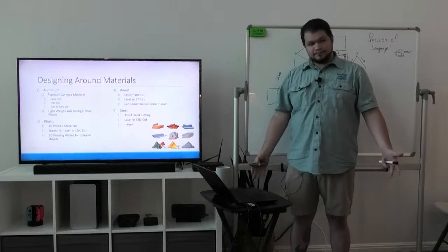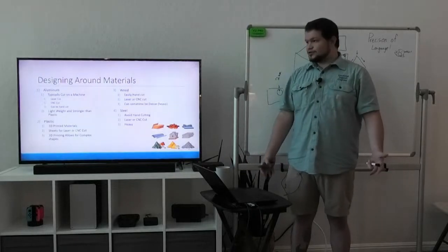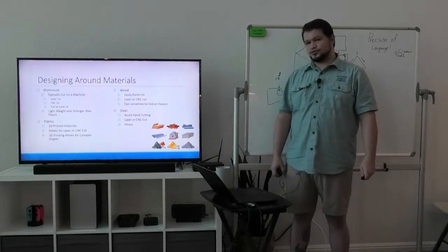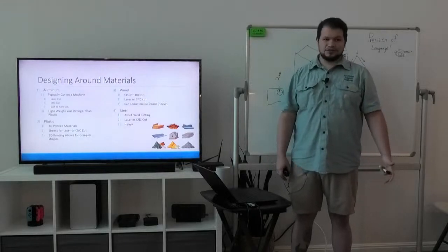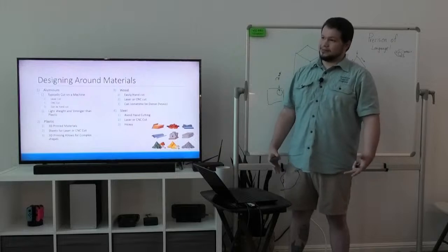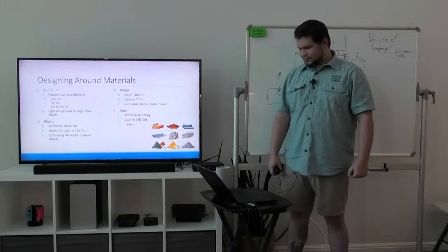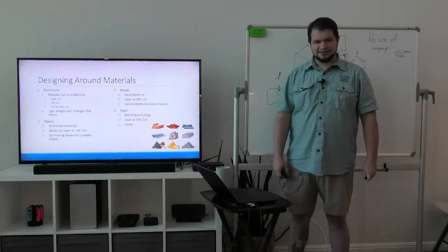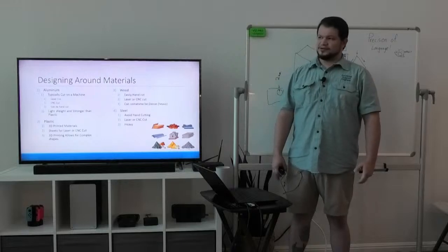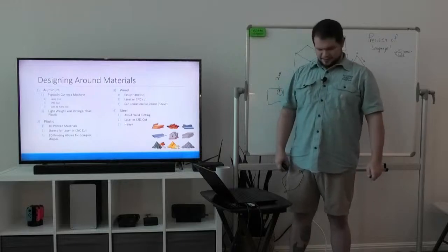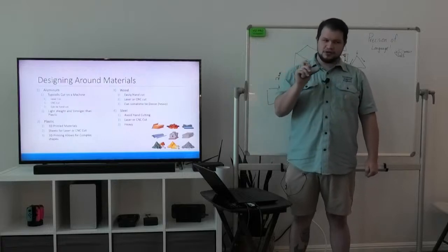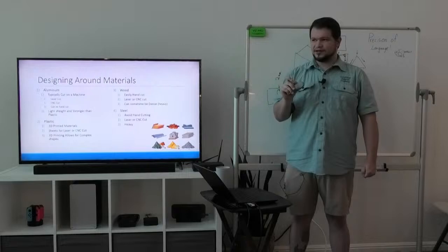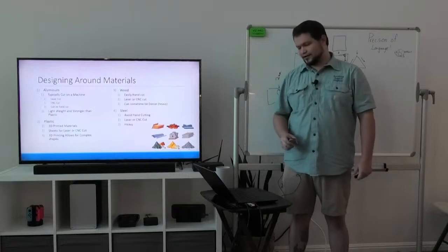You can use wood pretty easily on a robot. It's a lot easier to work with hand tools as opposed to aluminum. You can cut it with a laser or with CNC so that you can get the same level of precision. Sometimes it can be very dense compared to plastic, for example, or sometimes even aluminum. You can get a thinner aluminum piece with the same strength as wood, and that allows it to be lighter.